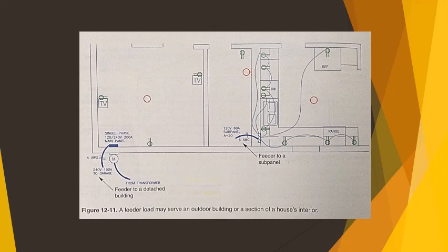This method reduces the number of conductors that run this distance from many 12 AWG to a few 3 AWG or 4 AWG wires. The total of all branch circuit loads and feeder loads is the service load.